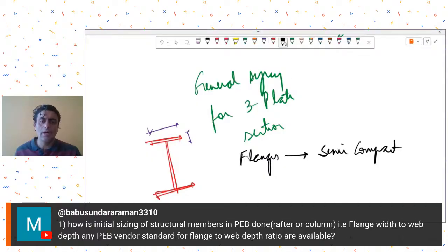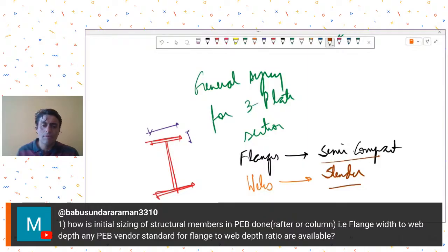of your IS 800 2007. And for webs, the general principle most of the pre-engineered suppliers follow is that they will take the webs as slender, because slender flanges are not allowed as per the current revision of IS 800 2007, although now it gets allowed in the NBC update.